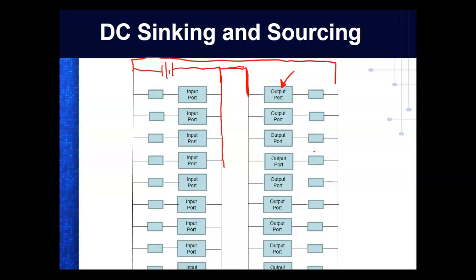You can't run a load, but it's usually around 2 amps. The problem is that the little old power supply there cannot supply 2 amps. So if all you had was push buttons and stuff, using it to run inputs would be fine. But normally the output is going to have an external power supply. With 2 amps, I know we can't run a 10 horsepower motor, but we could definitely pull in a motor starter, and that motor starter could run it.